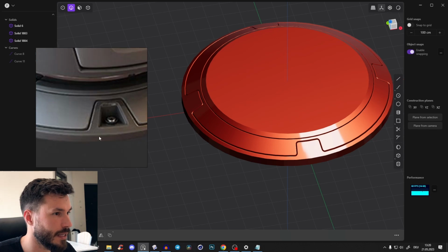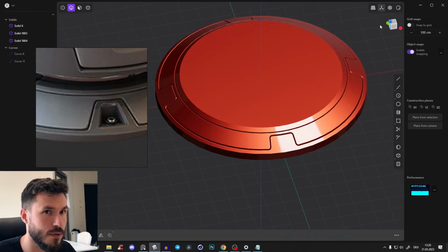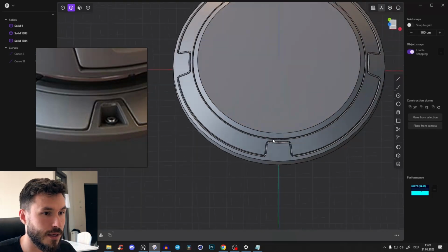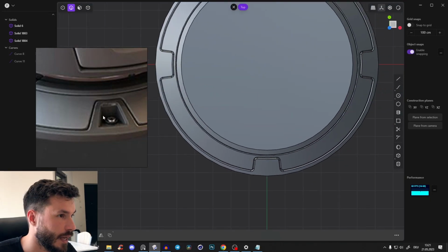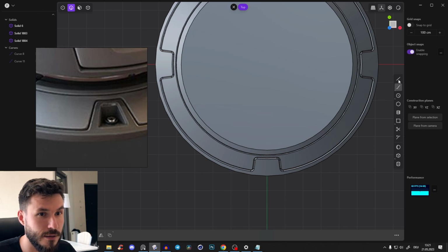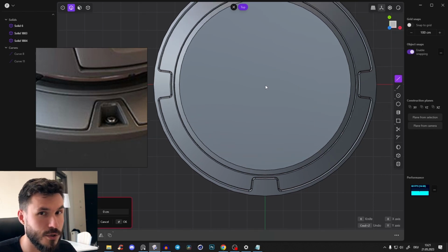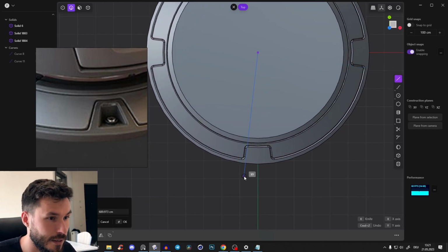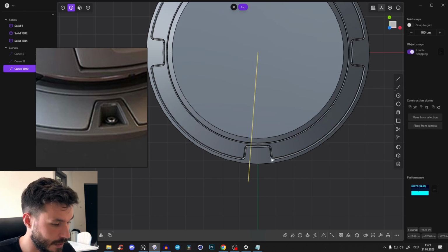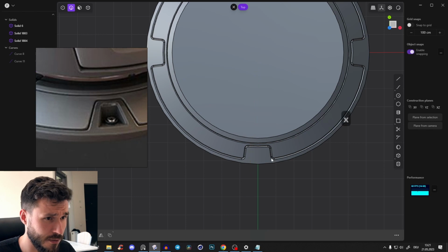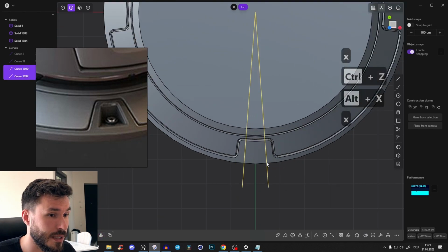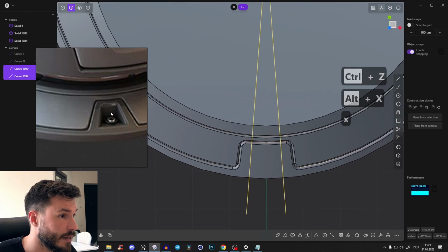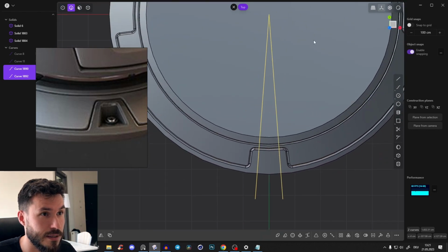And now let's create those holes here. So right click again, show edges here to the normal mode, and I go to the top view, and we see we have again a little angle. So I will just create a line and drag it here to the middle, and make it somewhere here. And again, Alt X to mirror it, not X, Alt X with X. So we mirror it, and let's do it like really exact.